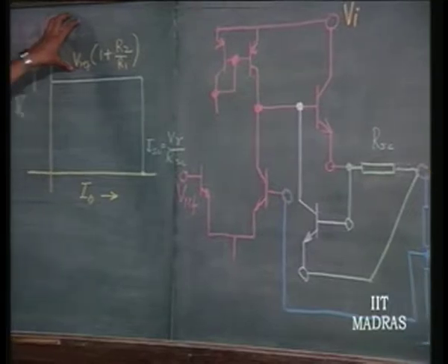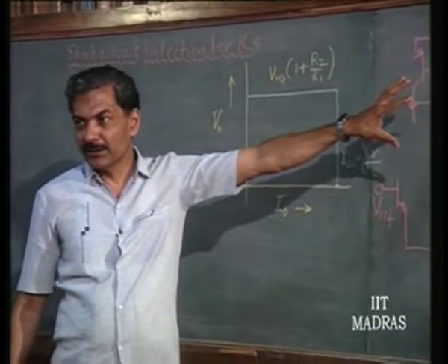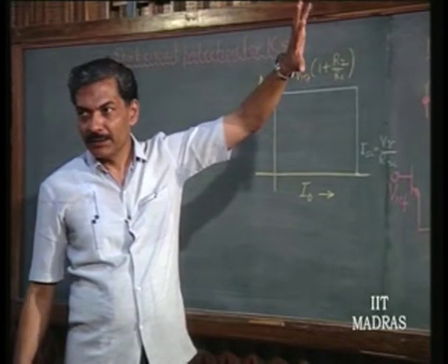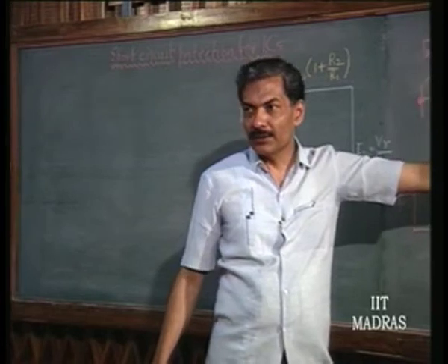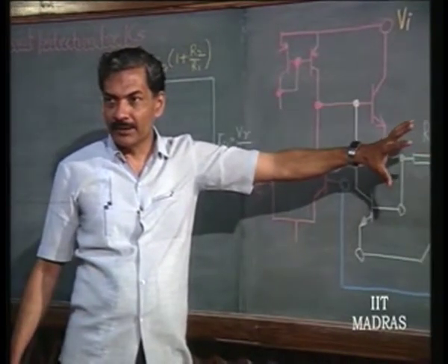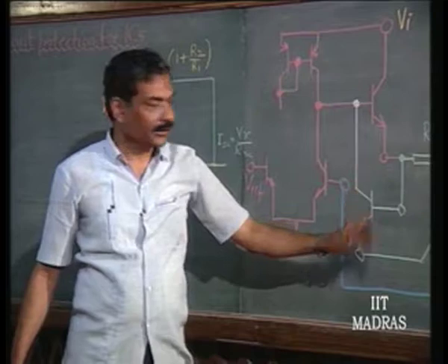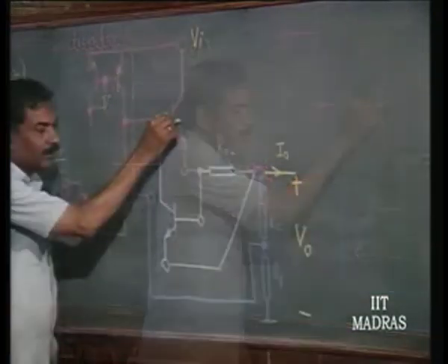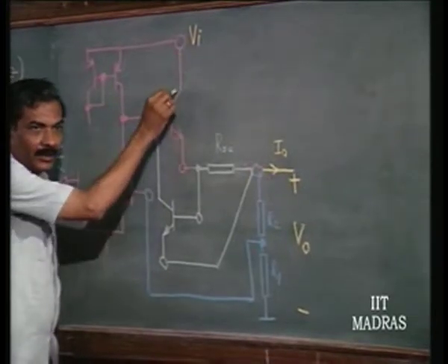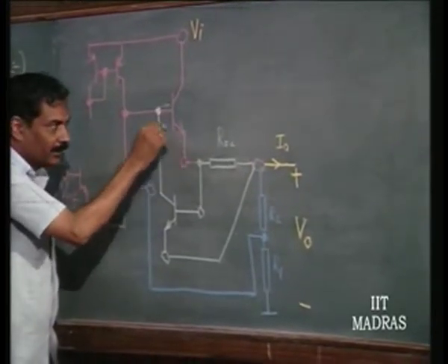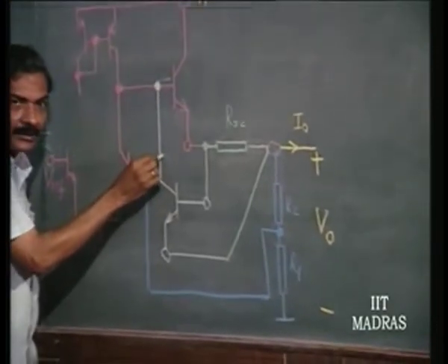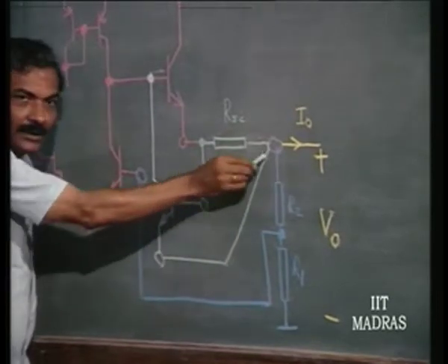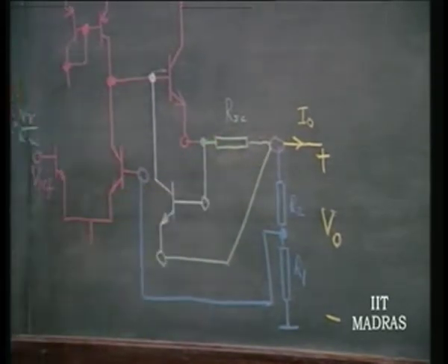Whether it is the voltage regulator IC transistor or power IC transistor, whatever it be, this is the common method of short circuit protection adopted universally in all integrated circuits. Once again, the drive that otherwise would have increased the current through the power transistor is diverted onto another transistor which is getting proper biasing because of the current increase.